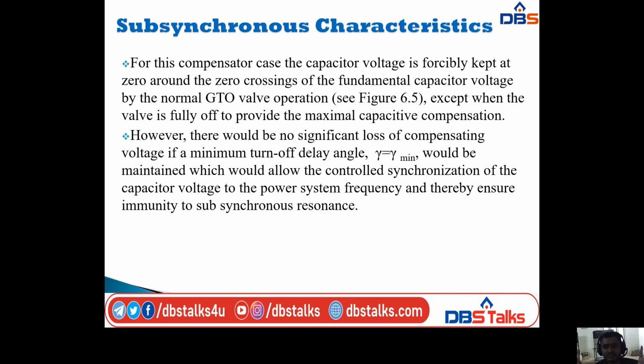However, there would be no significant loss of compensating voltage if a minimum turn-off delay angle, that is gamma, equal to gamma minimum, would be maintained, which would allow the controlled synchronization of the capacitor voltage to the power system frequency and thereby ensure immunity to subsynchronous resonance.